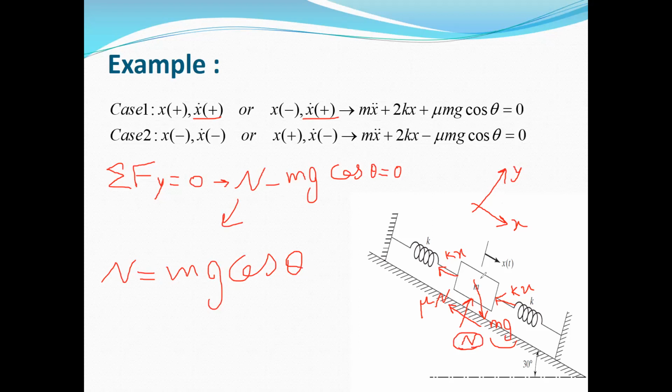Now we can write the force equation in x direction, but pay attention: when you are writing the force equation for a vibrating system with weight and initial deflection, you can neglect the weight in your equation, and you should also ignore the initial deflection in these two springs. So when you write the force equation in x direction,